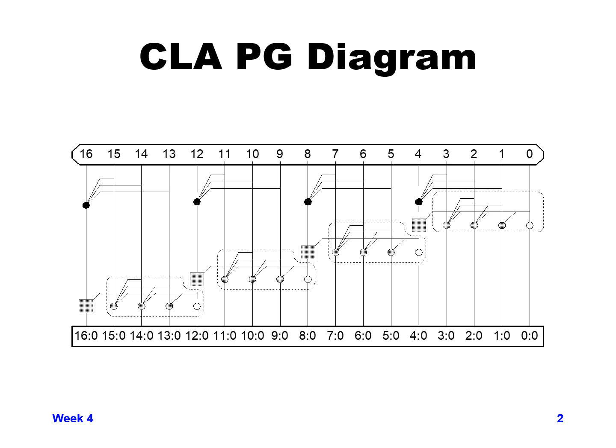Those are generally longer delay stages because they have lots of inputs, plus 3 normal carry skips in the middle, the gray squares. So the total delay would be about 5 stages, 2 of which are complex logic and slower, and 3 of which are faster normal carry skips.